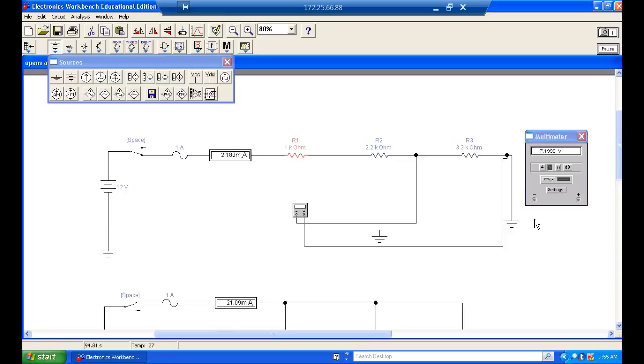This is what we're talking about. In a series circuit, sometimes a short will cause other things to fail. So usually in my series string, if I don't have a spare bulb, I just pull it out a little bit and twist it, and two wires short together, and all my other lights come back on. But what you've got to understand, instead of dropping 2 volts, each one of them is dropping a little more, which makes them a little more susceptible to blow.